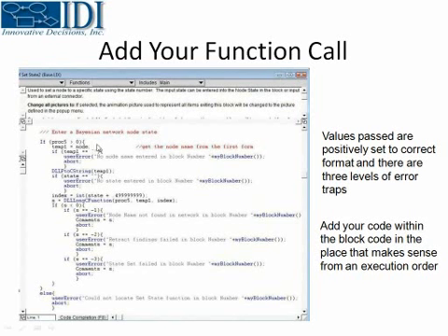Assuming that everything's installed correctly and there is no error code, then I'm going to set my node name to a variable called temp1. Node is actually the name of the variable within the block that is typed in the first screen when you open the block. And then I'm going to do another error check. I'm going to check and make sure that temp1 is not equal to nothing. So again, if there's nothing in that block, I'm going to trip an error message that says no name has been entered in the block.